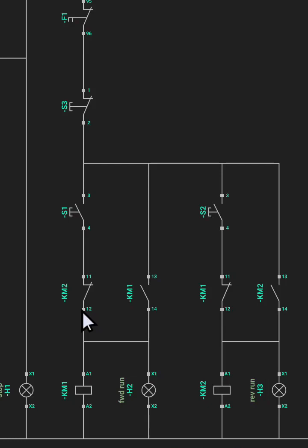So what this means is this: for the forward contactor to come on, the reverse contactor has to be off. And for the reverse contactor to come on, the forward contactor has to be off. Once the forward contactor is off, this place remains closed, and if it is on, this place remains open, so that the reverse contactor will never come on. Now we know what this normally open contact is. We have said it before, it is a returning contact.